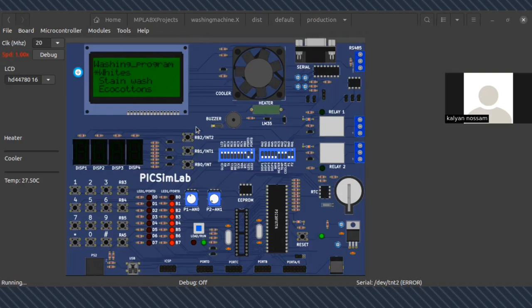The control of the timers has been executed very beautifully, and due to the debouncing effect, the key press is slowing a bit, but the small issue is not very impactful. If we increase the delay, this problem will be solved.